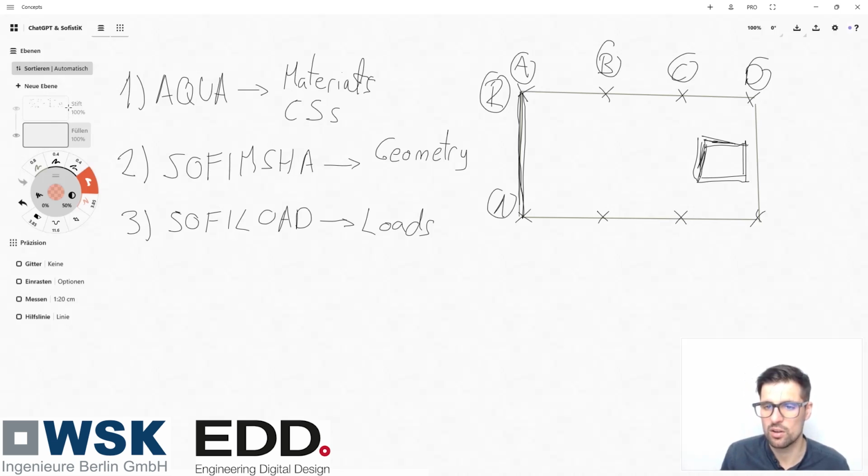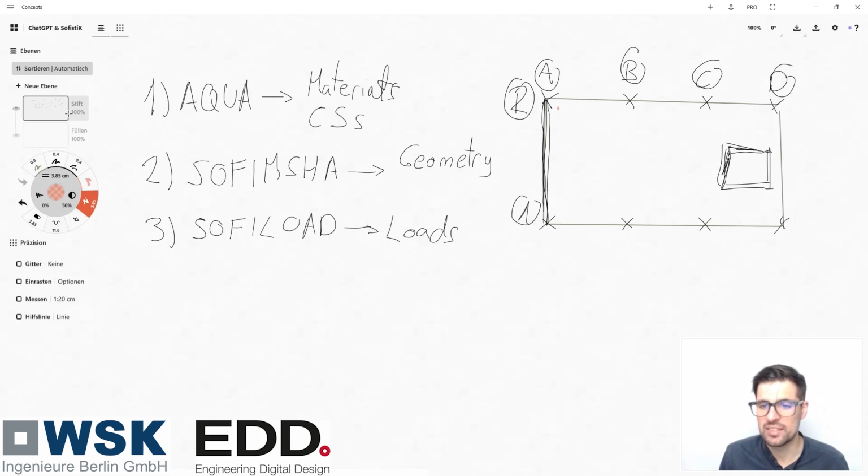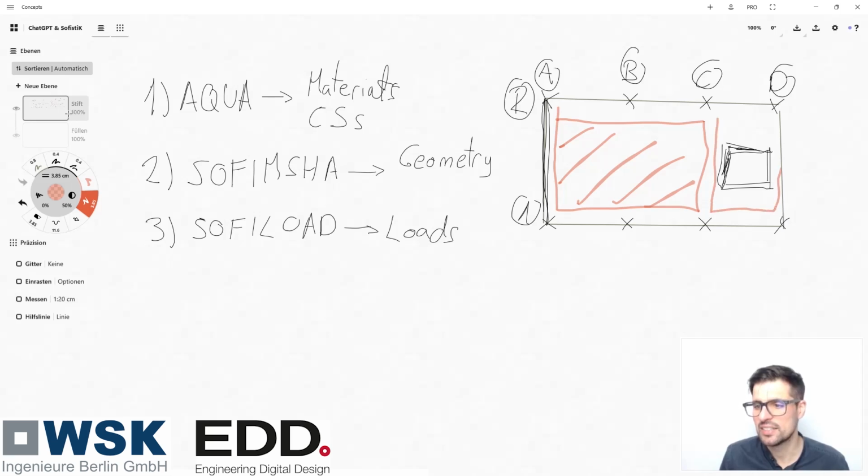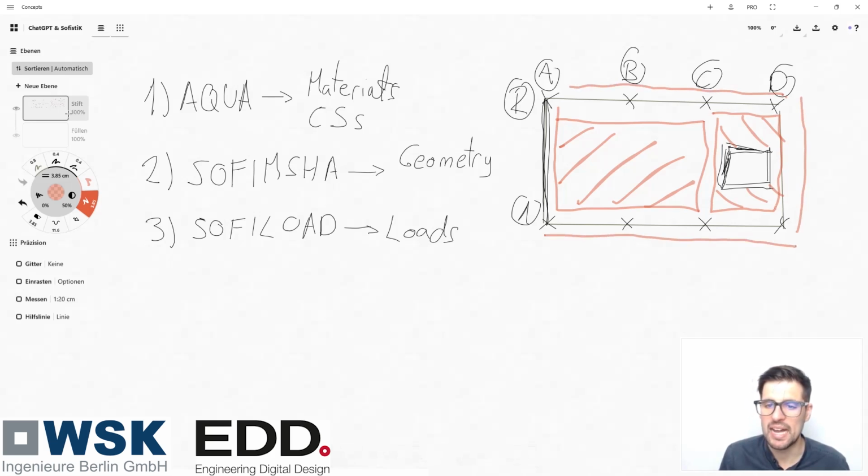So for instance, we are going to have a live load case with two different free rectangular loads, one defined on this part of our slab, and the other one with another value defined on the other part of our slab. Something like this. And besides these surface loads, we're going to define a line load, right, representing the building facade, which is going to follow the perimeter of the slab up until this concrete wall. Here over our line support, we're not going to draw any line load.